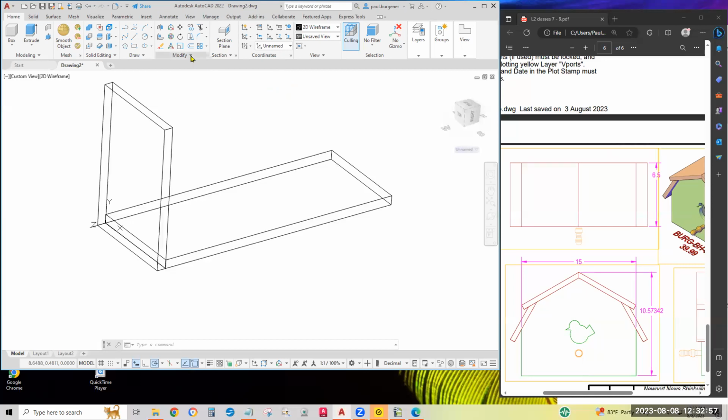That can easily be done with the old 2D mirror command. So we'll select this left piece that will eventually slice down smaller, hit enter. Oh, snap. Oh, we're on the XY plane. Okay. All right. I want to snap right here in the midpoint. So let's bail out, and I'll hit escape to get out of the mirror.